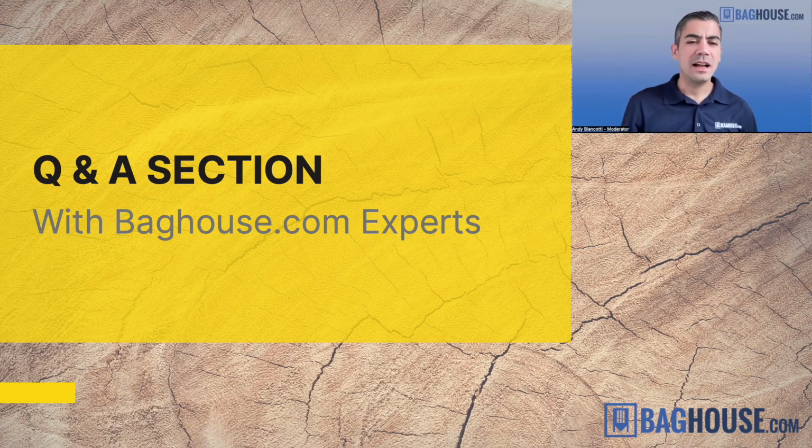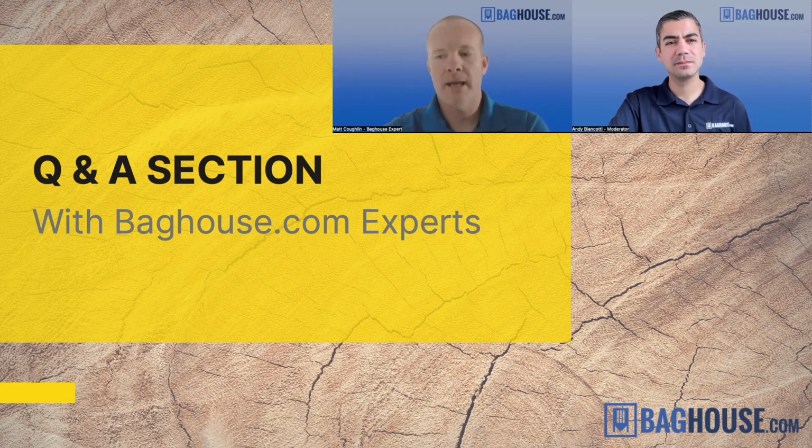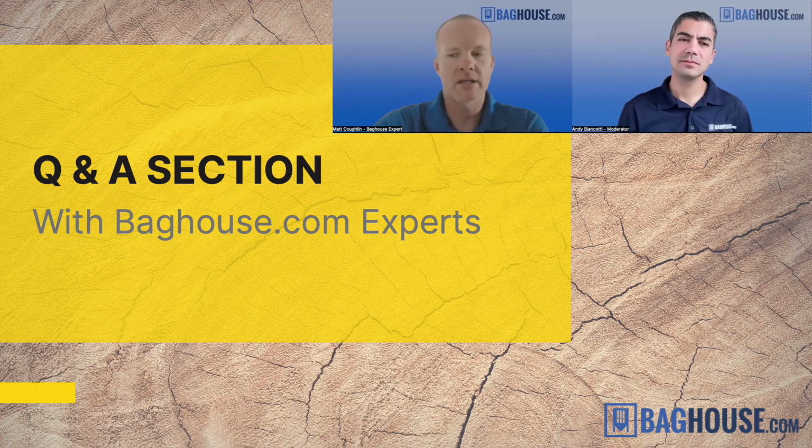Awesome. Next question. What are the warning signs that a dust collection system is undersized or not performing properly? So, classic warning signs. The basic functional metric for a baghouse or dust collection system is the differential pressure. That's the pressure across your filters. Usually, they're designed to operate between 2 and 5 inches water. That's the pressure range you're looking for.